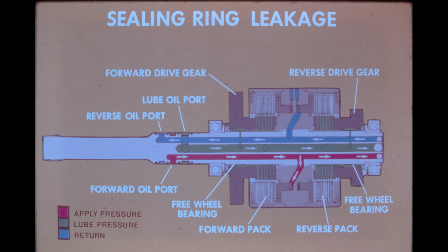If a low apply pressure reading on one gauge is not accompanied by a rise in pressure on either of the other two gauges, the leakage could be taking place across the sealing rings of the applied piston or in the internal delivery tubes.